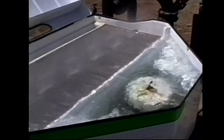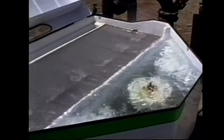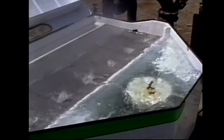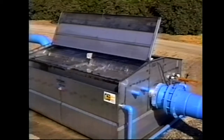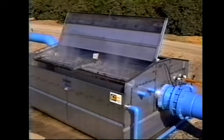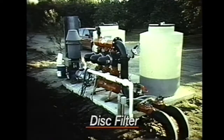The overflow screens are not the best choice if the water source is pressurized, because all of the pressure is lost at the entrance to the screen. On the other hand, if water is available with about 4 feet of pressure, these filters have the lowest energy requirement of any high-capacity filter. Overflow screens have advantages in that there is no backflush water to dispose of, and they can handle very high contaminant loads, including algae and sand.